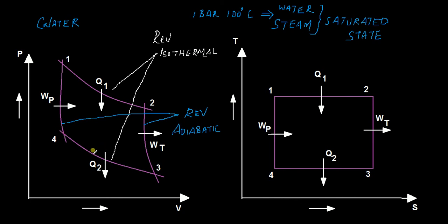And therefore you have lost some heat and changed the phase from steam to water by transferring the working fluid from 3 to 4. So you have a saturated water at this stage, at whatever pressure it is at. Now you need to compensate for the pressure loss from 2 to 3 by pumping this working fluid from 4 to 1. So you add some pressure from the pump and the working fluid is transferred from 4 to 1.